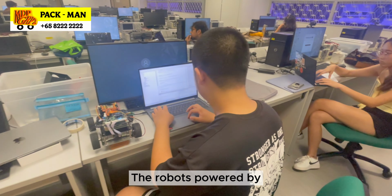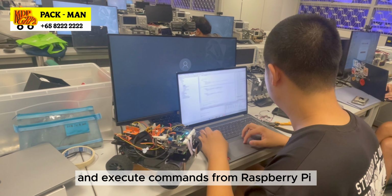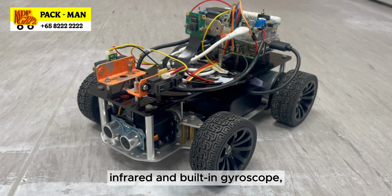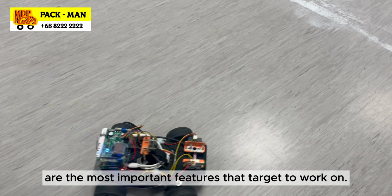The robot, powered by an STM32 board, is the foundation of all other parts. We built a card that can receive and execute commands from Raspberry Pi to accomplish different tasks. In addition, many sensors like ultrasonic, infrared, and built-in gyroscope are applied to help the robot to achieve the goal. Precision and reliability are the most important features that we target to work on.